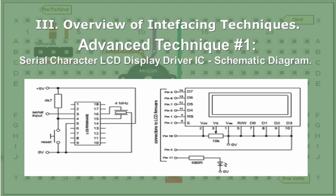They have a contrast control to set the contrast. These are very common, and there is a 44780 right there, probably. I think that's a 44780. You can see whether it's got a read-write pin. This is parallel input here. This particular one has parallel input, and you could have a chip that would take that serial data and translate it to parallel. I think the 44780 has that, if I remember rightly. But this is just some examples of some more advanced techniques.